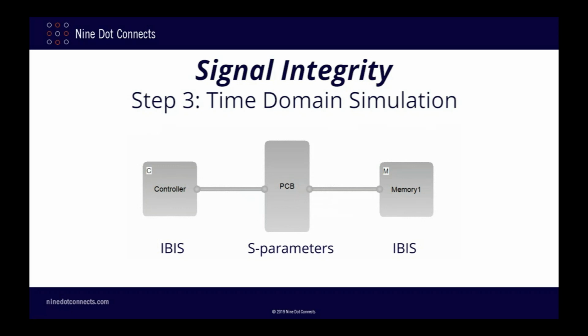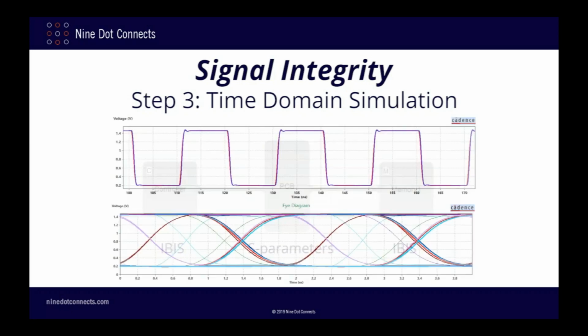of the device itself. Once I've entered these models into the System SI program and set up simulation parameters such as the clock rate, I'm able to generate different kinds of waveforms of my signals. These waveforms represent the system behavior in the time domain and are in the form of both the traditional waveform diagram as well as something called an eye diagram. I will talk more about eye diagrams later.